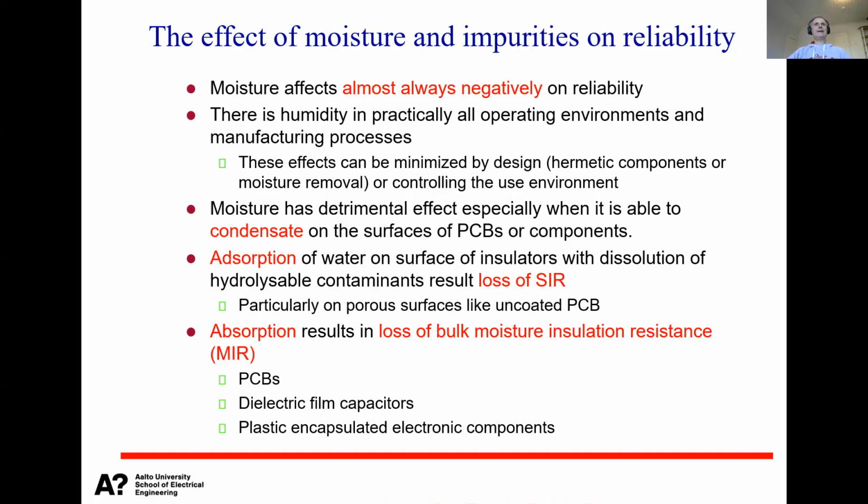You typically need to add something, conformal coatings, like what we will discuss with printed wiring boards, or molding compounds or silicone gels, which slow down or prevent the diffusion of moisture and impurities. But if you don't need them, then why invest money in this kind of protection?